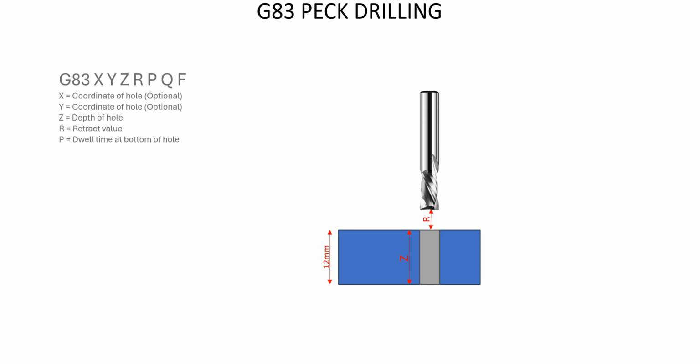If we are working in aluminium or other metals, we maybe want to break the chip so it's not getting longer and longer and curled into a lot of things. So we just put in a dwell time, and that will break the chip, and when it's retracting, it's just taken out without falling off.